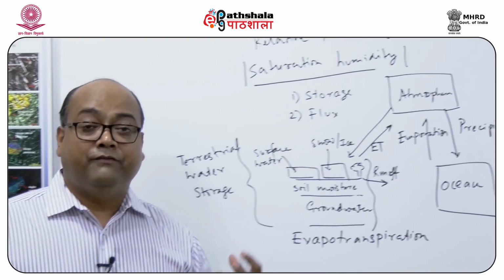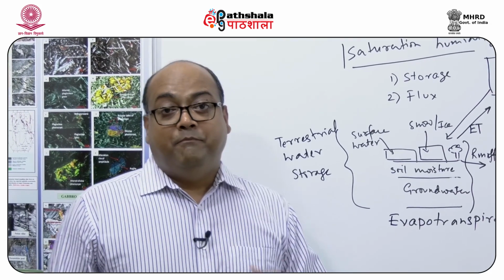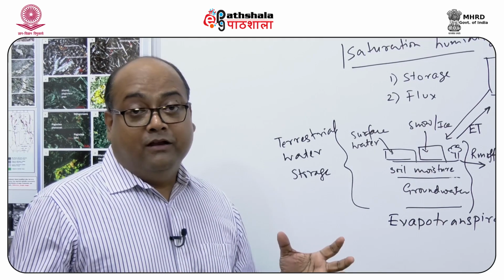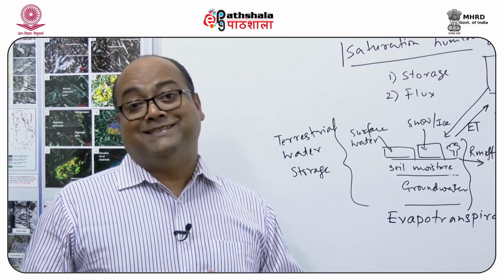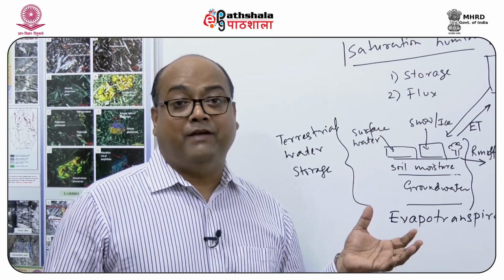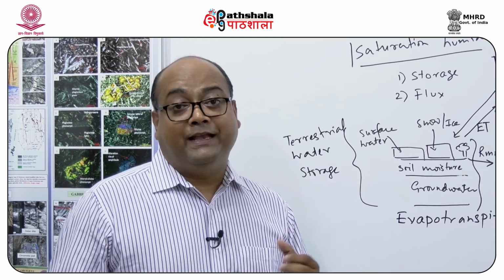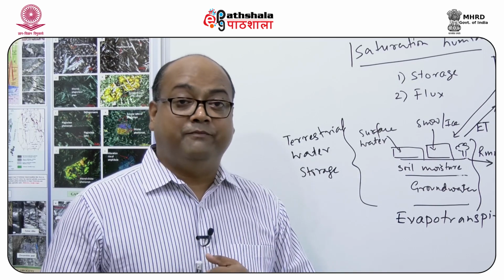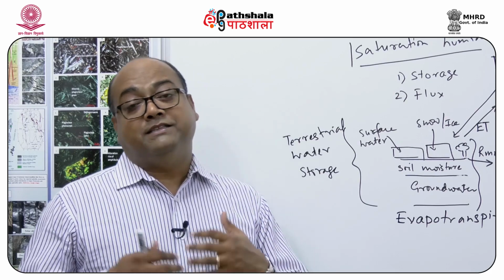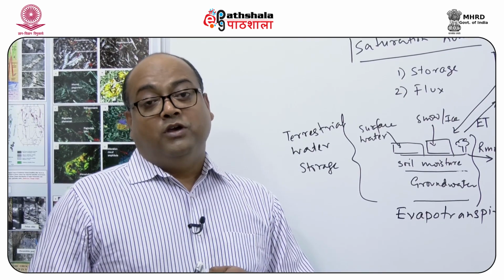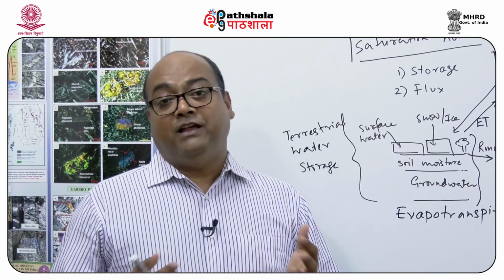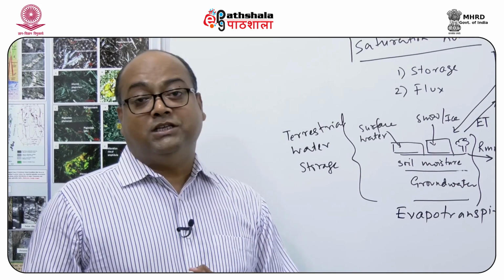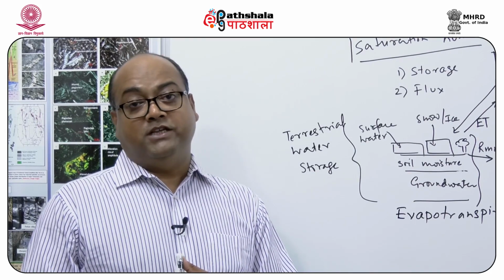By the heterogeneity in the plants, I mean that various different plants transpire at different rates. Evapotranspiration is a significant flux in the hydrologic cycle, but it is relatively difficult to measure. In open air or open water surface, evaporation is relatively easier to measure compared to evapotranspiration. This is owing to the fact that it depends on various factors, including different types of plants, because each and every plant transpires at different rates. So now people are working on eddy flux towers, which is one of the ways they measure, and some techniques have been developed to measure evapotranspiration using satellite-based measurements.